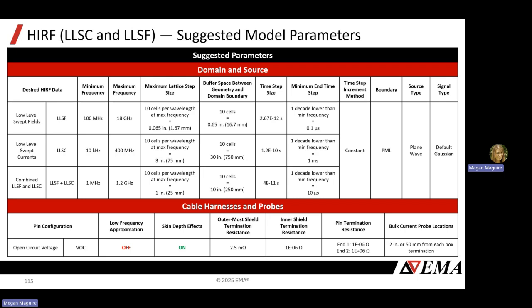Time step size will be dependent on your step size for your lattice. Your end time, you want to make sure it's 1 decade lower than your min frequency. So basically, your minimum frequency is what the simulation will tell you in the domain as the end time that you should use. Do 10 times longer than that so that you can get enough data at that lower frequency to be useful.